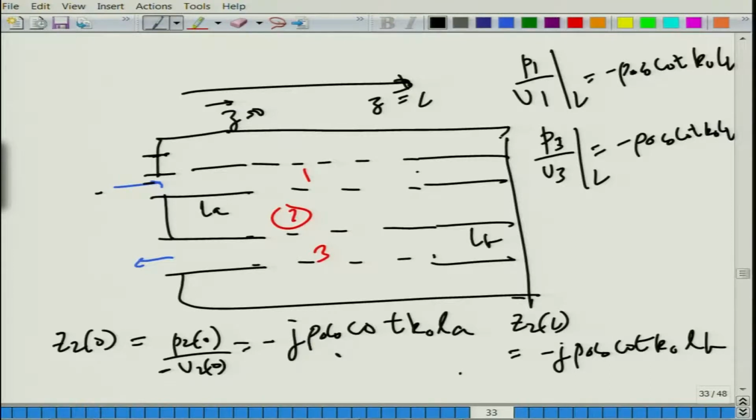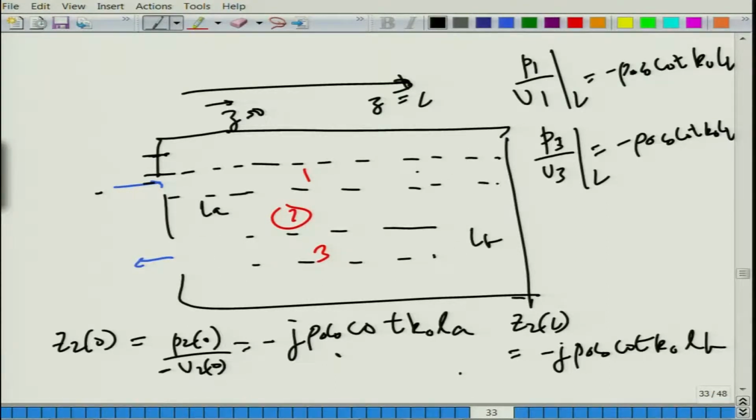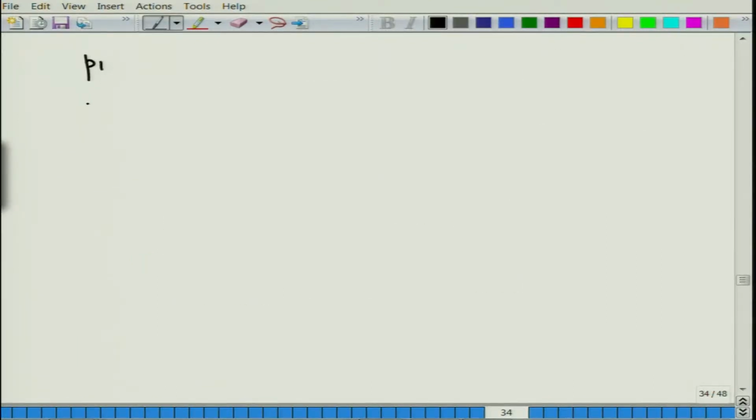So, now you can have a look at the text by Munjal for those boundary conditions. The simplification of that is rather tedious. So, what I suggest is a simple configuration, an extruded fully perforated duct. Here all these terms will be going to infinity. So, there are a lot of simplifications that one can do, and eventually if you write the state vector P1 to P3 and rho naught C naught U1, rho naught C naught U2, rho naught C naught U3